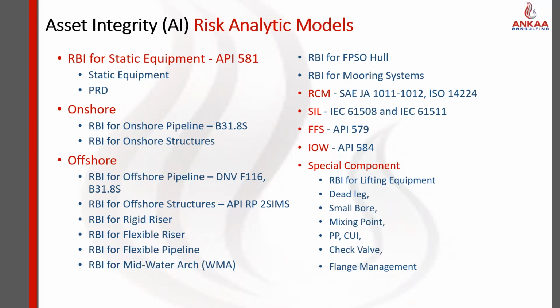RBI for hull and mooring, RCM for all your rotating machinery, SIL for all your shutdown systems based on IEC 61511 for the offshore industry. You should be able to achieve that. We have shutdown systems. It's a critical safety critical element. However, we go to great lengths in classifying it and verifying it during the project phase.